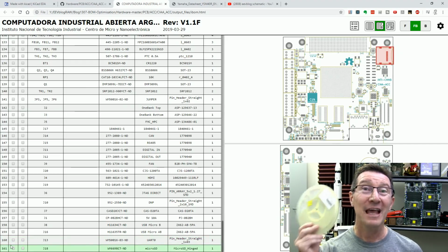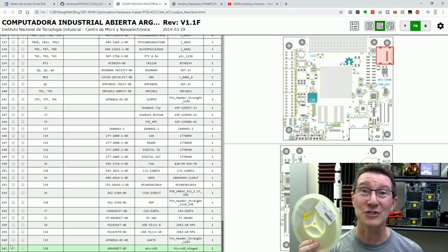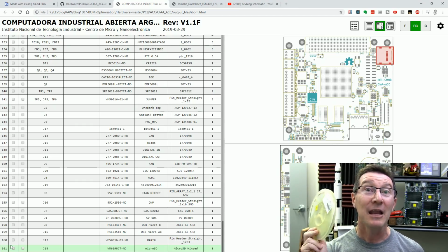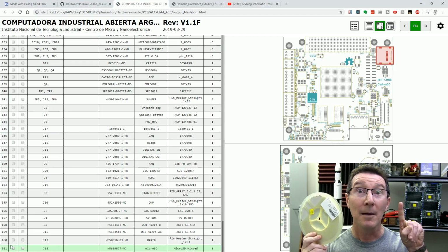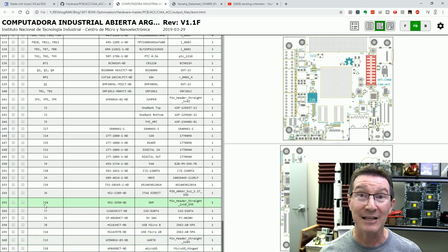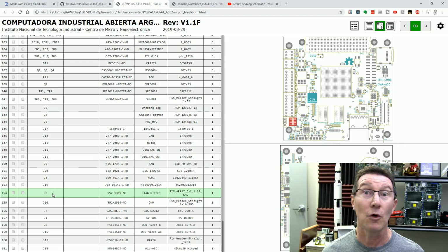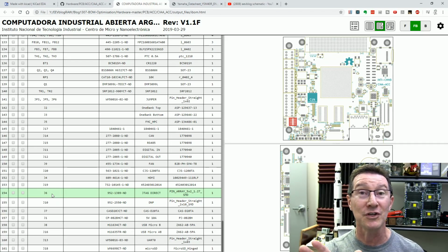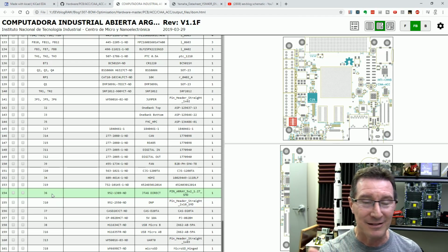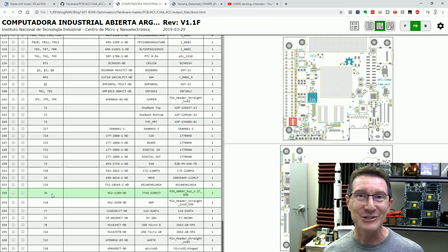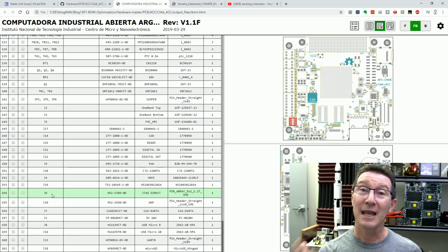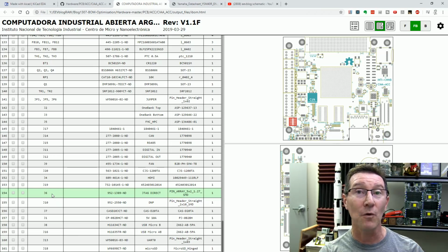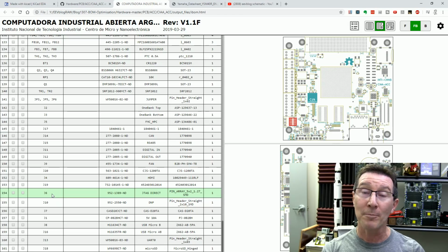But not only that, then you have to actually go out and buy and source all of these different types of parts, and just missing one part out of those 160 parts, you might not be able to get your product manufactured, or you could get it almost all manufactured except for one part. So the more different types of parts you use on your design, the higher the risk, the greater the potential assembly cost, and all sorts of issues to do with that. So reducing the different types of components is what we're talking about here in terms of BOM optimization.